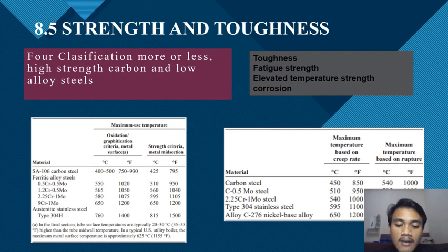The most effective and economical methods of improving fatigue strength involve designing the part to eliminate stress risers, avoiding sharp surface tears or indentations that may result from punching, stamping, shearing, and even hardness testing, preventing the development